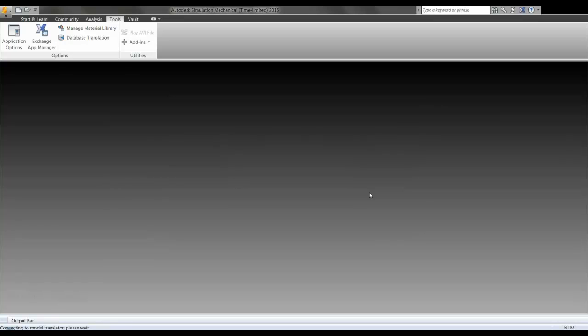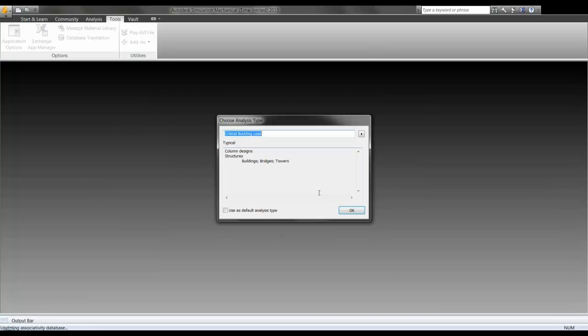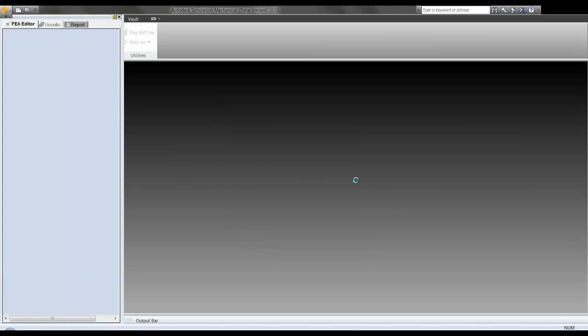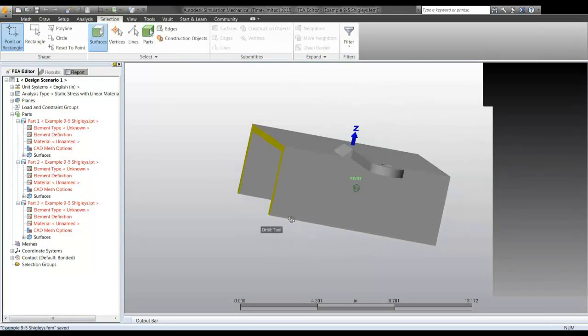I built these models in Inventor. Unfortunately, I had to hand build the actual fillets for the model due to unintended design features in simulation. Weldments do not transfer across from Inventor into Simulation Mechanical at this time. Certain welds do, most do not, unfortunately. So the welds had to be physically modeled in the CAD beforehand.